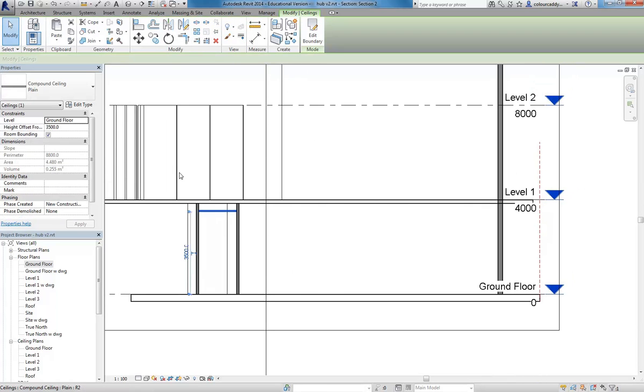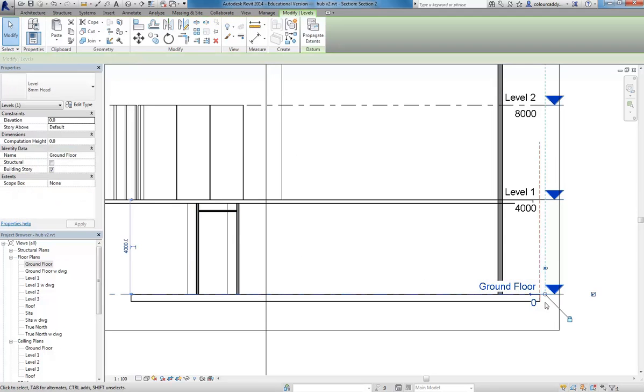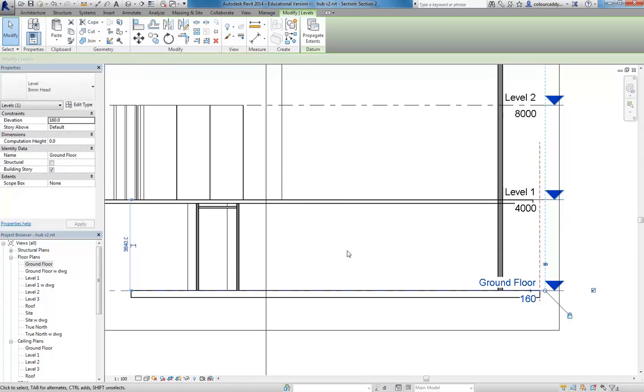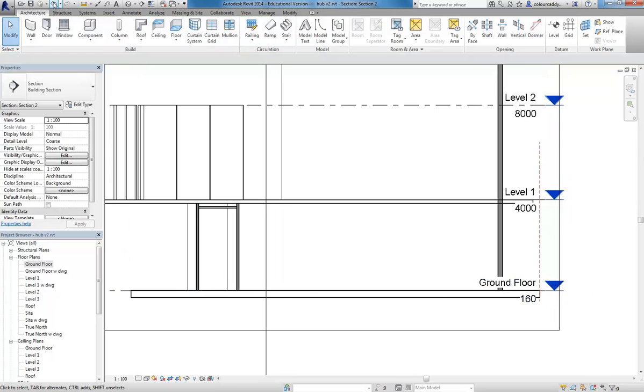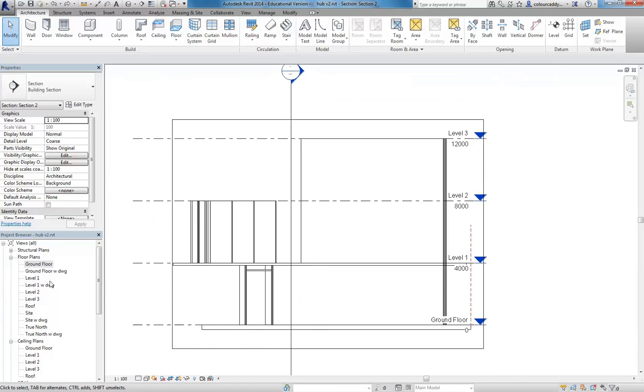So that ceiling there, you can see I've just put a height in here from the ground floor level. Just type it in. And for me it makes sense because I know then that's 3.5 metres. Even if this floor moves, it's going to maintain that ceiling height, which is usually what I want. Okay, so that should, like I was saying, give you plenty.